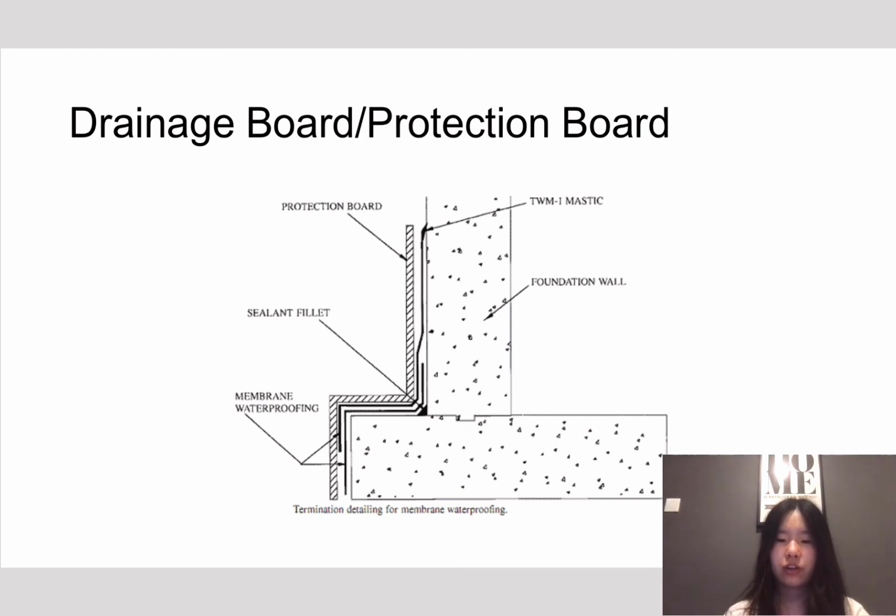And in this case, I choose to use independent foundation of reinforced concrete material. It's economic and simple, and the construction is simple and fast. It can be poured on site, and although it cannot bear relatively large loads, it should be no problem for a three-story building. For the possible damage to the foundation from groundwater in Malaysia, foundation drain was also selected.